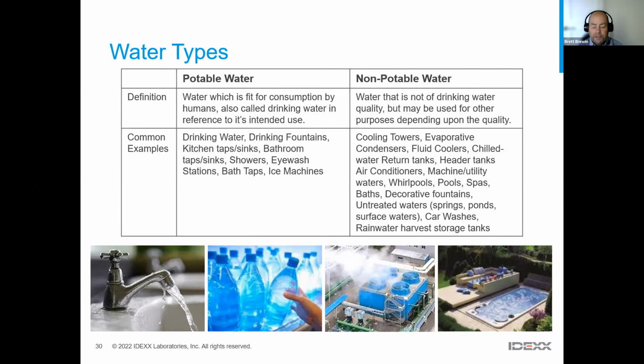The main point, however, is anywhere where you are potentially producing aerosols, so cooling towers, fountains, anywhere that you're going to be producing aerosols, testing for Legionella pneumophila is extremely important, because that's the root of infection. The aerosolized particles are inhaled, they infect the lungs, and that can in the end result cause the disease.